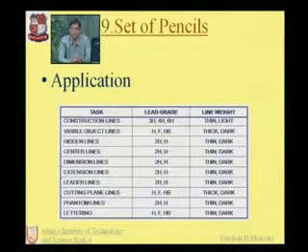The third one is the hidden lines. If you want to draw hidden lines in any machine drawing or engineering drawing, in drafting we have to use 2H and H grade leads, which are thin and dark. The next one is the center line. Same here, we use 2H and H, which is thin and dark.